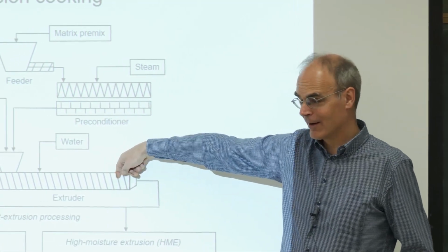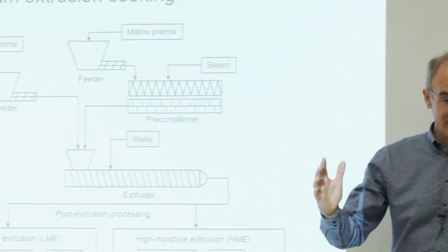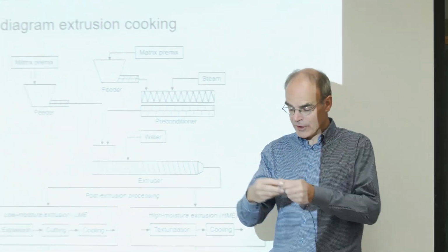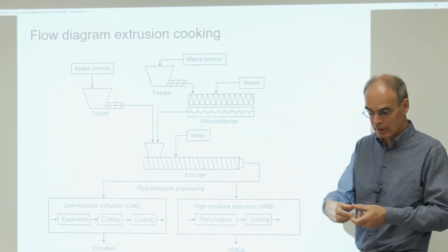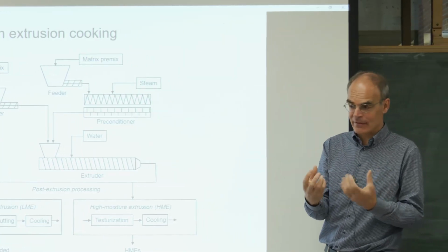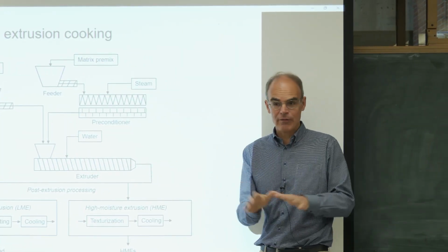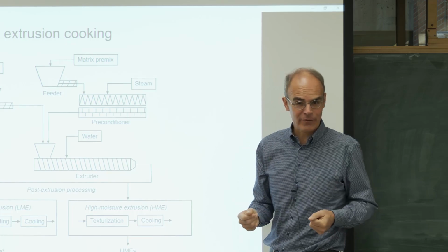Good. So then we extrude, so we have high moisture extrusion, that's with that cooling die. In that cooling die, we shear the protein, so there's a phase separation between the protein and the water. Then we stretch that into these lamellae, and it sets in that structure that you saw yesterday. You have all been seeing the extruder. You have also played with the materials.